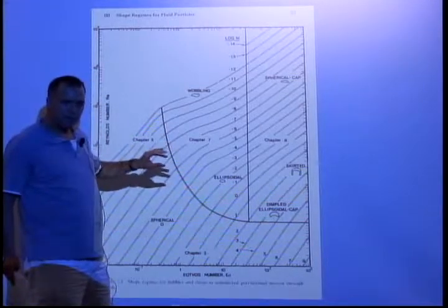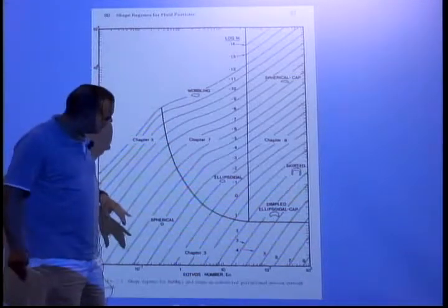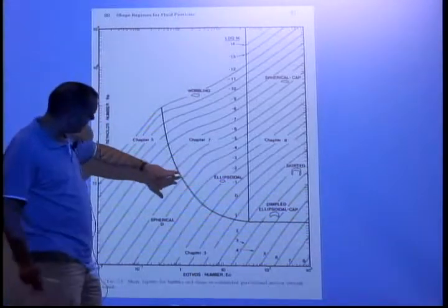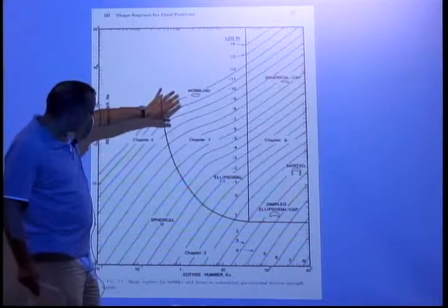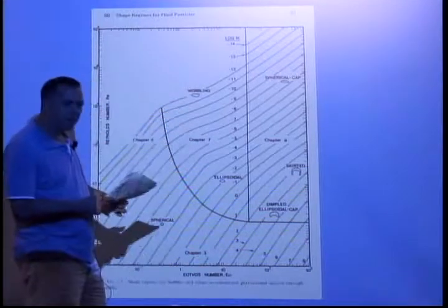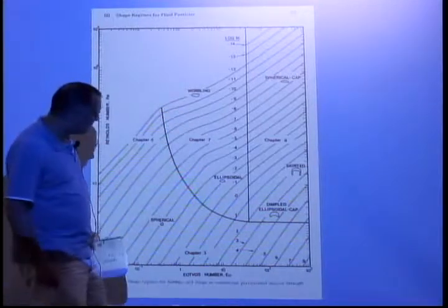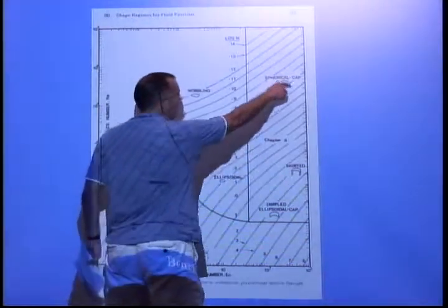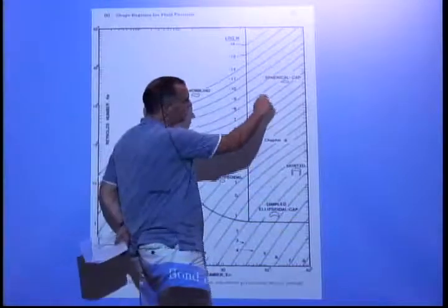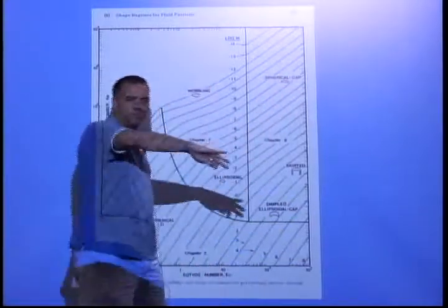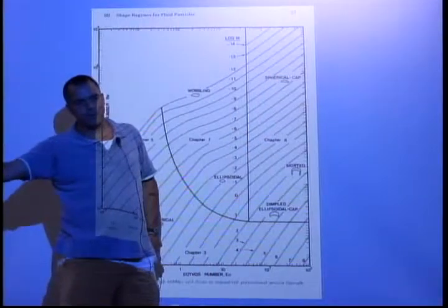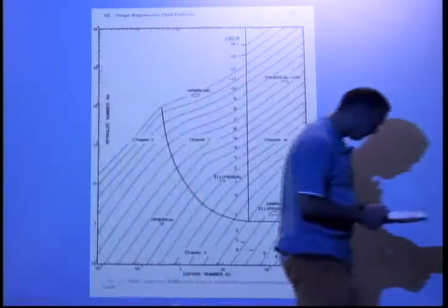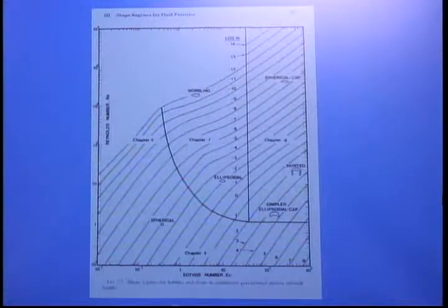And then as the drops become bigger, they get deformed in response to dynamic pressures. We've seen the onset. First things go ellipsoidal, and then you get unsteady motion: wobbling motion, spiraling motion, and then highly deformed shapes. The interesting thing is, and we'll go through this, there's a limit where the bubble is very big, and it's a spherical cap, and it doesn't break up, and we'll see why in a moment. So it actually doesn't need surface tension to maintain it.